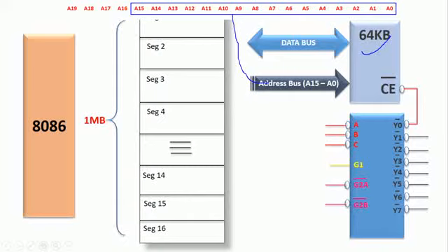Remember, allocating the address lines to the memory device is always done from right to left format. That means you should move from the lower order, the LSB bit of the address lines, to the MSB bit. You are not supposed to move from left to right.